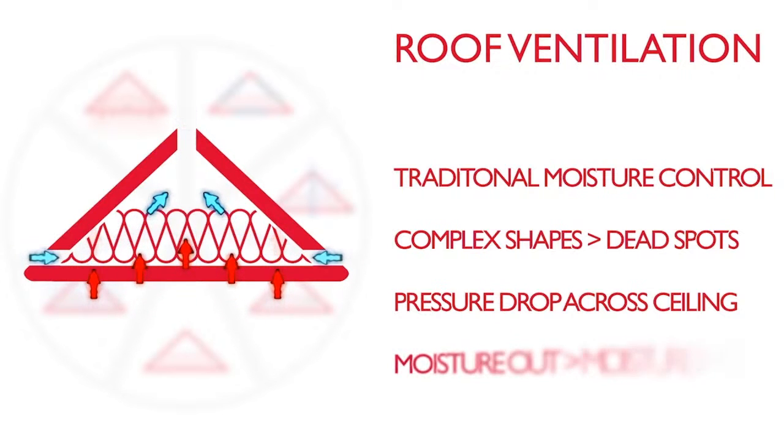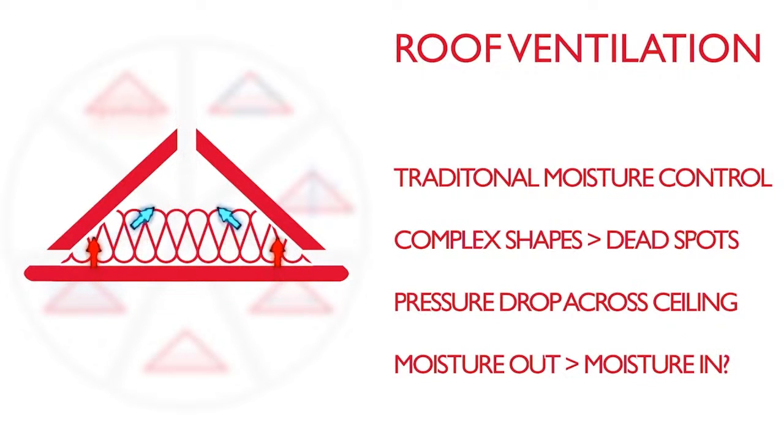There's also the potential for issues arising from the ventilation openings themselves, which, if they can let moisture out, can also let moisture in. If not properly designed, these openings can allow the ingress of windblown rain or snow, and if not correctly installed, they may not provide the design airflow rates on which a dry roof depends. Ridge vent systems may also be more susceptible to moisture ingress during construction, as there may be an opening present at the ridge even once the underlay is in place.